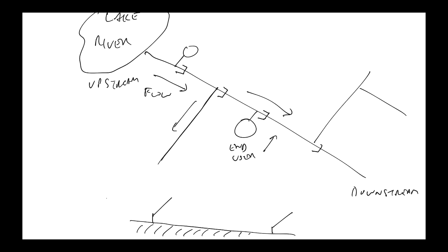All right, and so in order to deliver the required quality of service to the end users, there was a tendency to oversupply. Release more from here than was actually required, just to make sure that the water levels were sufficiently high to allow gravity-powered supply to the end users.